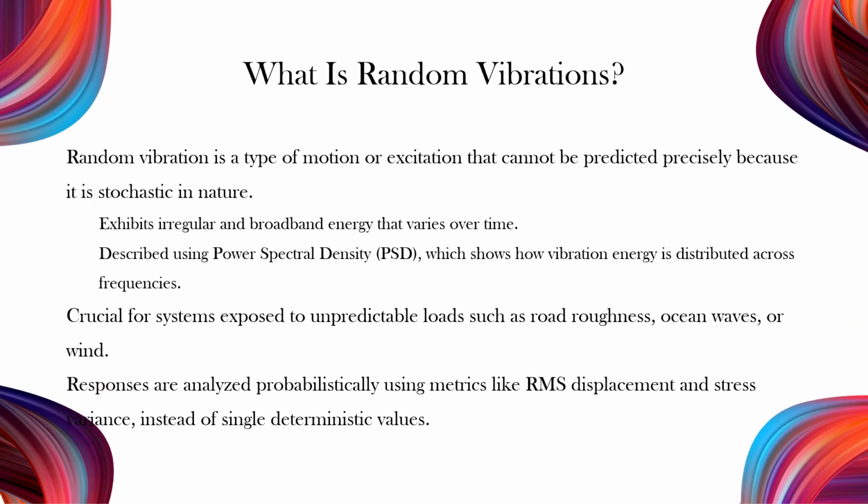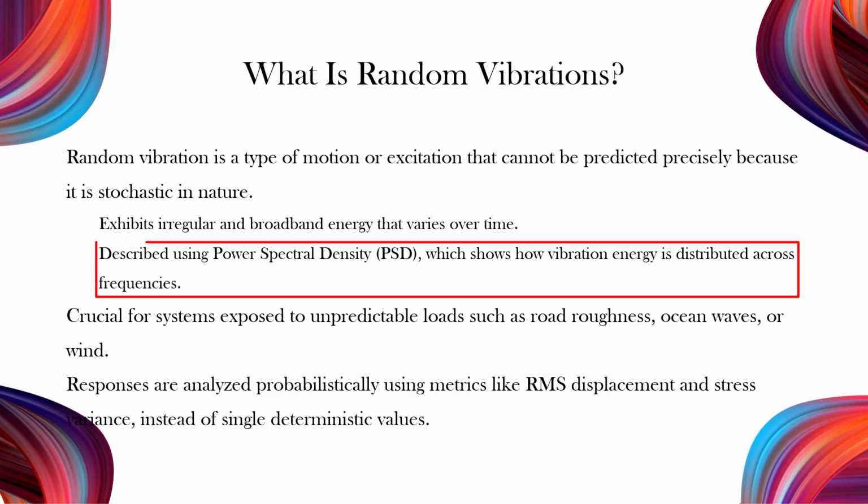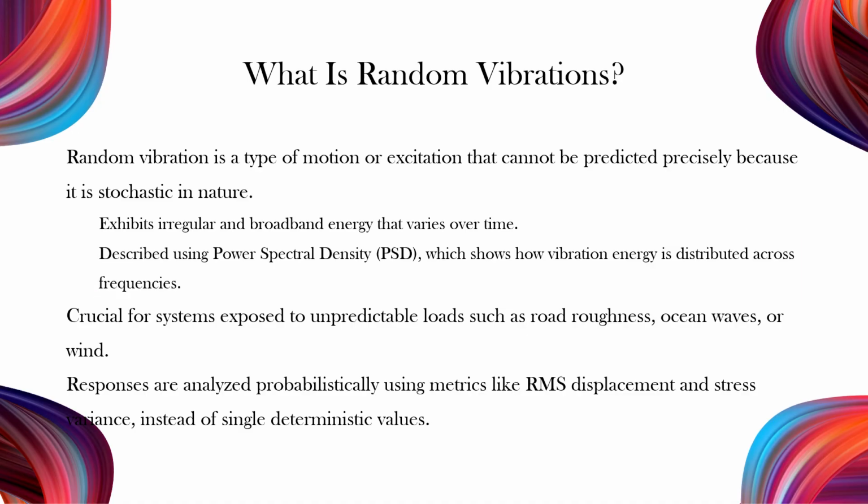Random vibration refers to motion or excitation that cannot be predicted precisely because it is stochastic. In simple terms, it shows irregular and broadband energy that changes over time. Engineers describe this behavior using power spectral density, PSD, which shows how vibration energy spreads across frequencies.